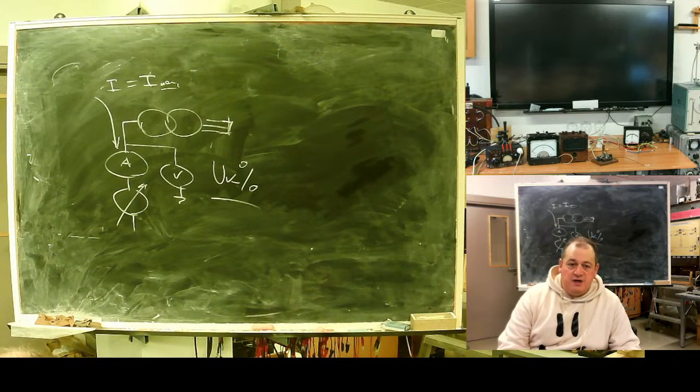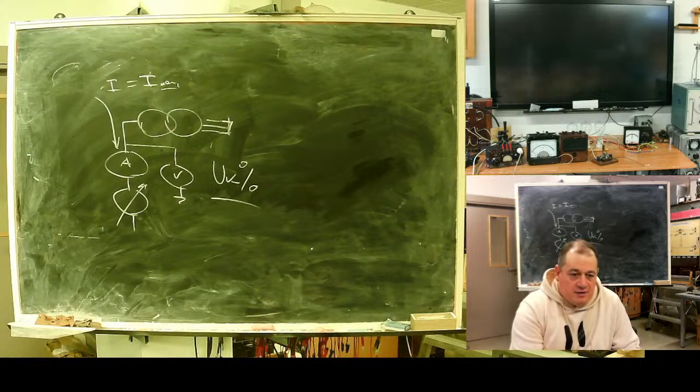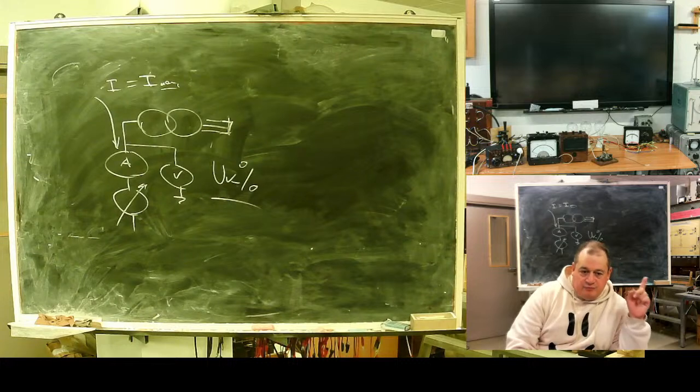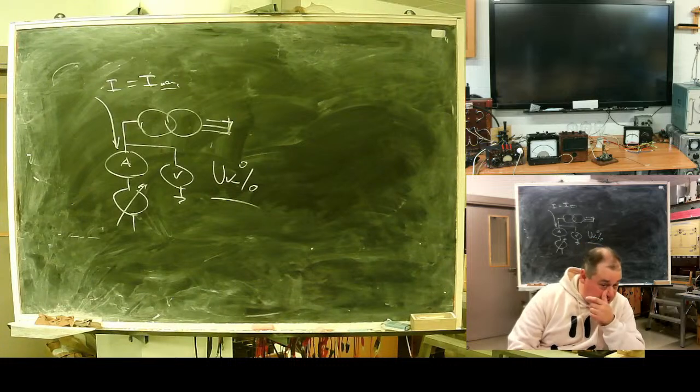It's interesting that this voltage in volts, in real named values, is very different for different transformers. But here in Latvia, take any 110 kilovolt transformer, and they all will have 10.5% of this voltage.